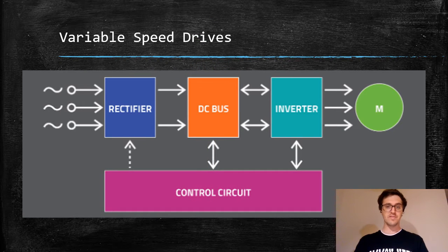Variable speed drives can be used to ensure the HPGRs are continuously operated with high throughput. Overall, they are essentially AC to AC converters. A three-phase AC with fixed magnitude and frequency is supplied, and an AC with different magnitude and frequency is output. As an electric motor's speed is frequency dependent, the drive allows the speed of connected motors to be controlled.